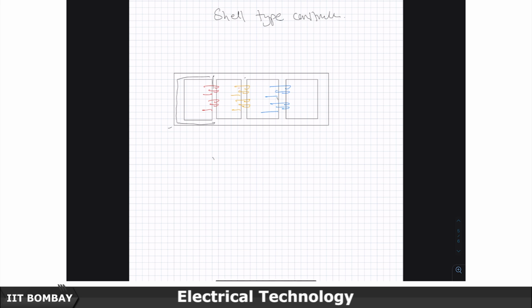return path like this. So similarly, this flux will come here and then it will come like this, but will not fully burden this, it gets another path to come like this. Similarly, this flux will break, will get two paths to come, it will not come directly start flowing leftward, because there is another limb to break it through. So it will break here, then it will break here, it will break here, and then it will come back, and then it will come like this.